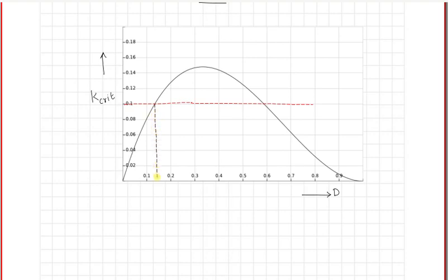So clearly this point and this point, if I put it down, then you can say that in this region of operation of D, you have your 2L by RTS, right? So this is 2L by RTS, the value for this converter, and therefore during this region of variation of duty ratio, you have 2L by RTS greater than the k critical.